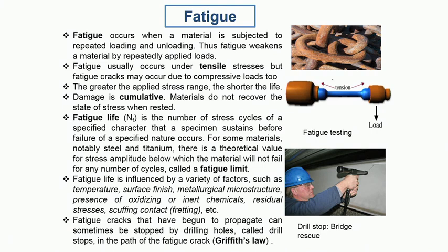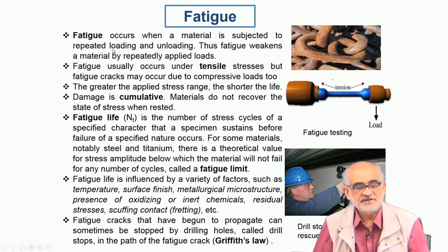But what is important is that the load is applied in a cyclic manner. So whenever we see such cyclic loading, the solid component is going to experience loading and unloading cycles. And in this kind of situation, almost all engineering materials are known to fail at a level which is lower than the yield strength.